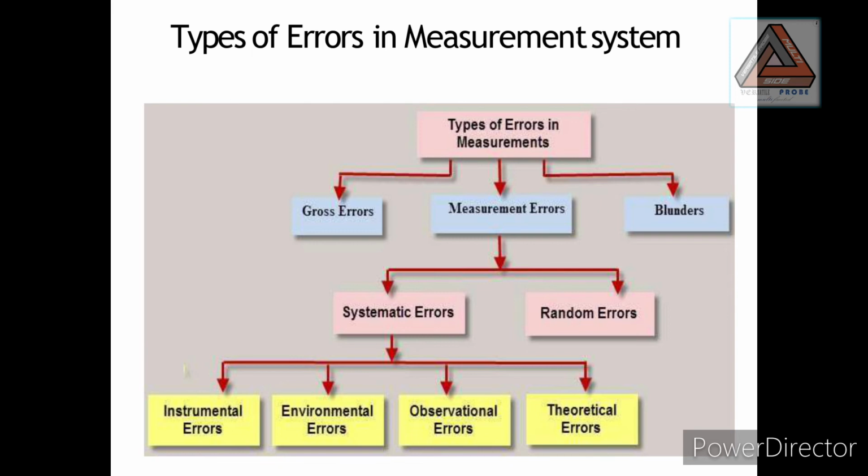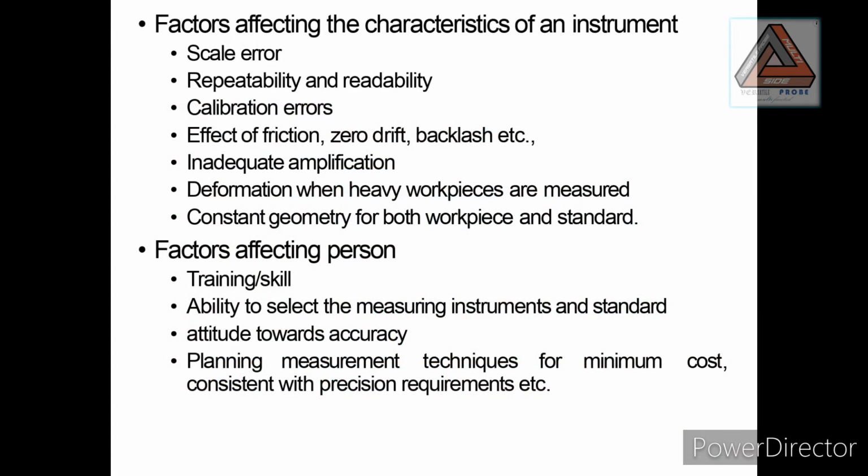In that, the gold shop has a closed container to measure the gold gram weights. Why? Because gold is more costly comparatively than vegetables. Temperature, dirt, humidity and vibrations are the 4 environmental factors that influence the measurement. If the container is not available and the fan is rotating over the weighing machine, the gram reading may increase due to the density of the air.